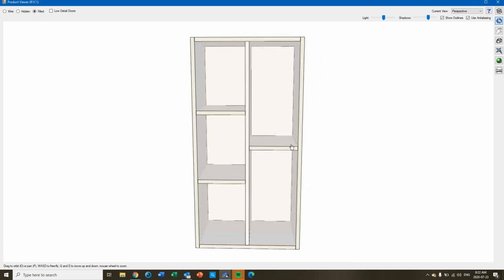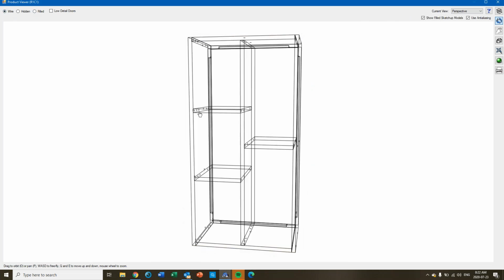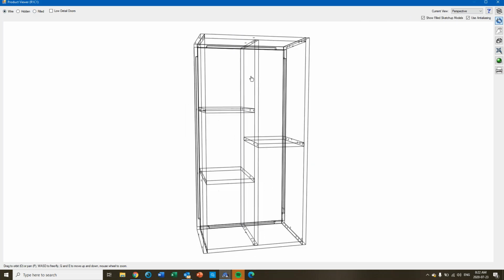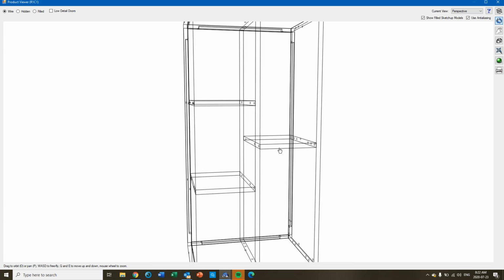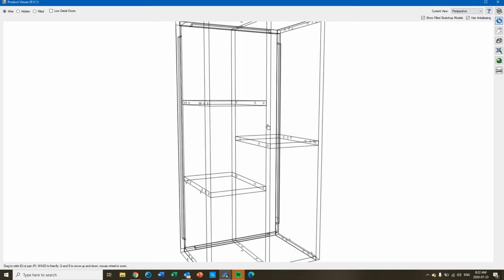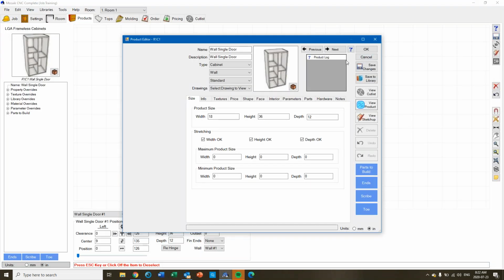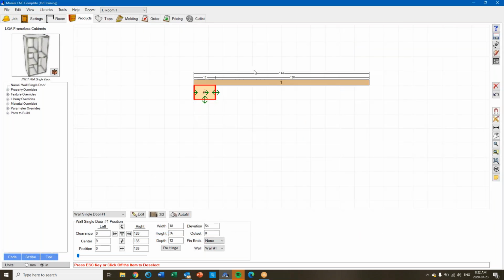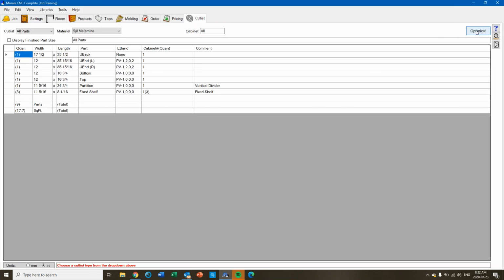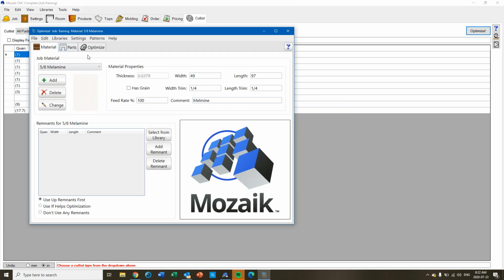But now look, I have a dilemma. I have a partition, and no matter what method you want to make cabinets, you cannot avoid a flip side operation right here. Because I have 1 part, 2 fixed shelves. Of course you could get rid of your dowel holes or put 2 partitions in or something, right? But to do what I'm showing you, no way around it. So it's an obvious example, and I'm a big fan of really obvious examples. So I'm going to nest this part.